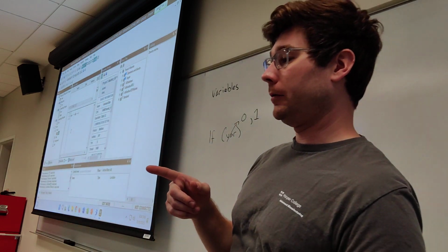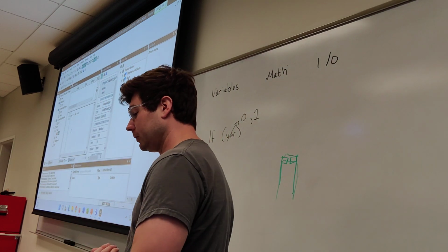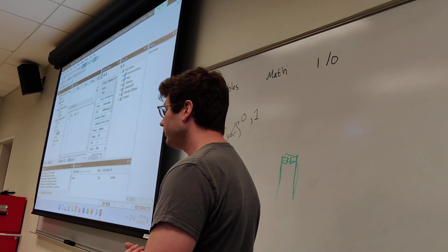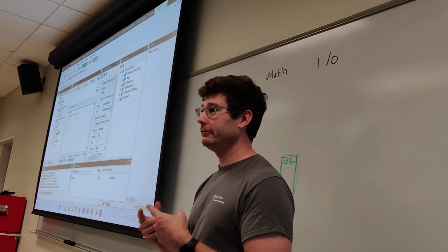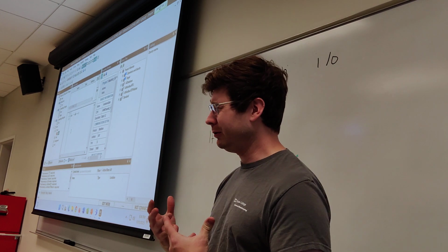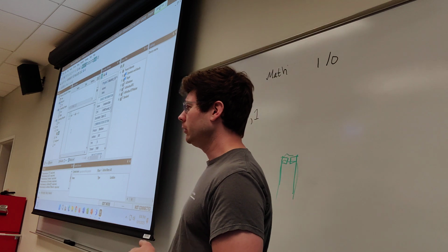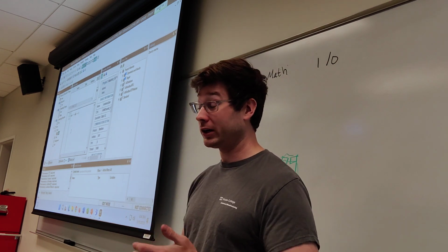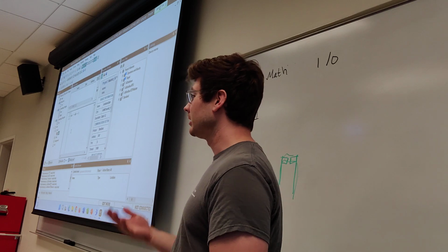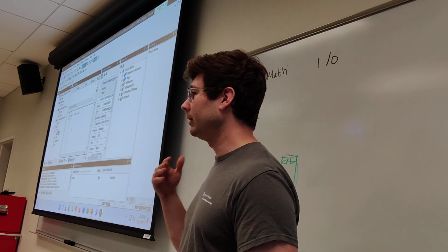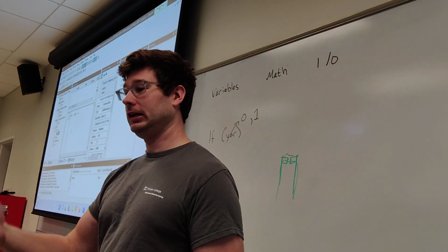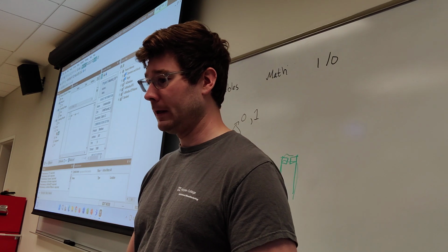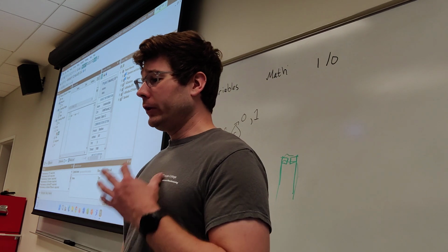Okay, 1 second. So by putting, for example, things that need to run really often, like real-time processes, in the fast task group, almost everything we do goes in the fast task group. Lazier processes, or things we don't really care about updating really fast, or computationally intensive processes go in the background task, right, that runs every half of a second and doesn't really care about timeliness, okay? Think about that, really important.